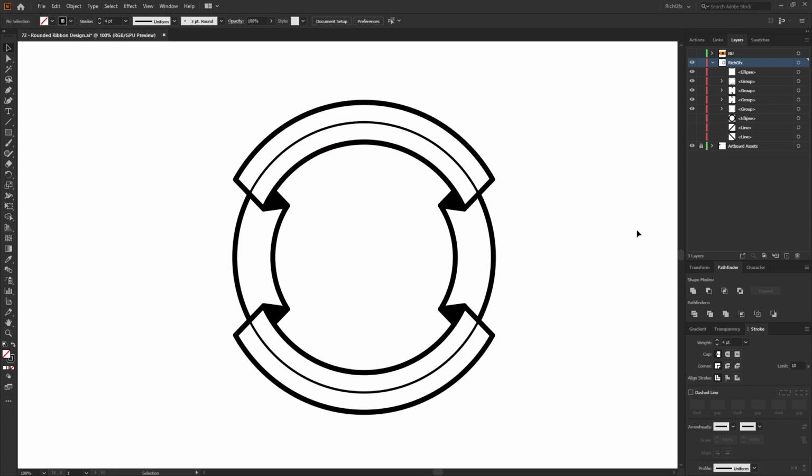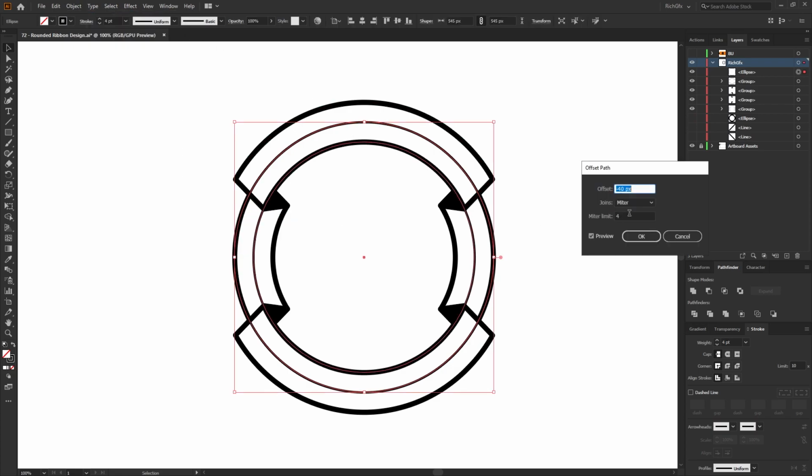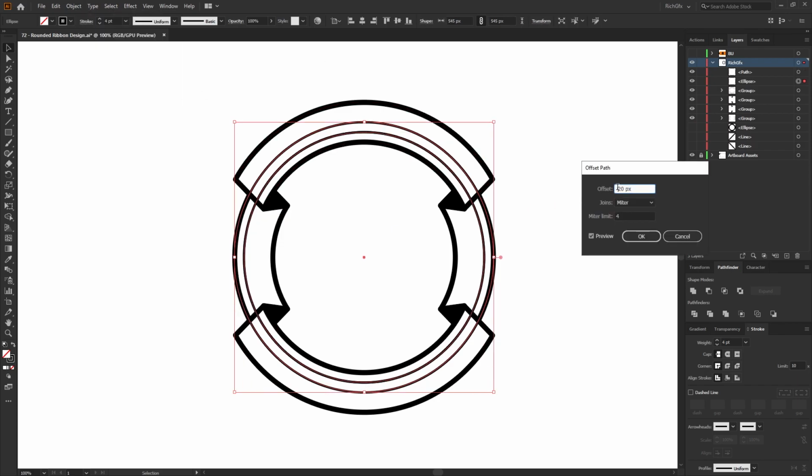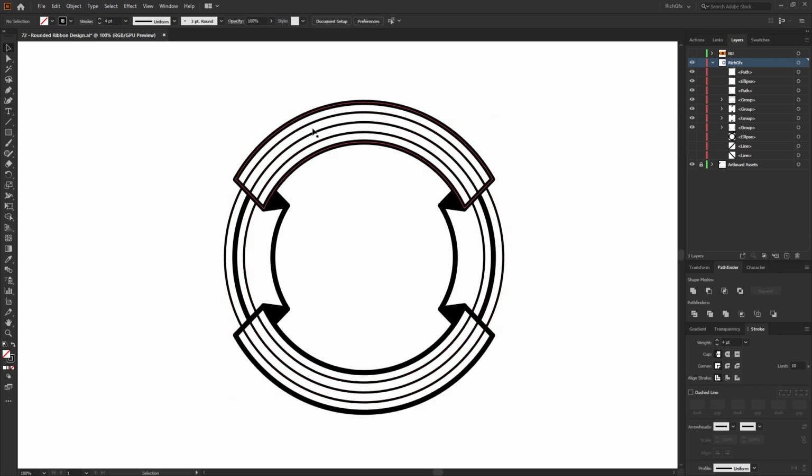ellipse within the artboard. As everything was horizontally and vertically centred from the start, the ellipse should fall directly in between the top and bottom parts of the shapes, which means what we can do is select the ellipse and go to Object, Path, Offset Path, and we want to offset it by -20 pixels. Reselect the original ellipse and go to Object, Path, Offset Path, and then change it to 20 pixels. So what you should end up with is 3 different size ellipses.